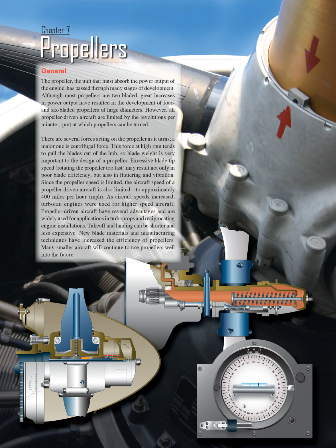There are several forces acting on the propeller as it turns. A major one is centrifugal force. This force at high RPM tends to pull the blades out of the hub, so blade weight is very important to the design of a propeller.